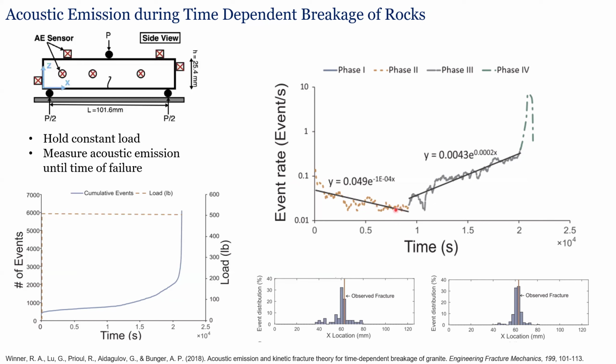So for, in this case, a bit over 40% of those 8 hours that the specimen survived this load, there is a declining event rate. But then it turns around and for hours is experiencing this slowly increasing event rate before a final burst at the end. So we found this kind of interesting because actually there was this long period of time where you can see it's accelerating to failure. And if we didn't want it to fail, you could imagine we could have intervened.